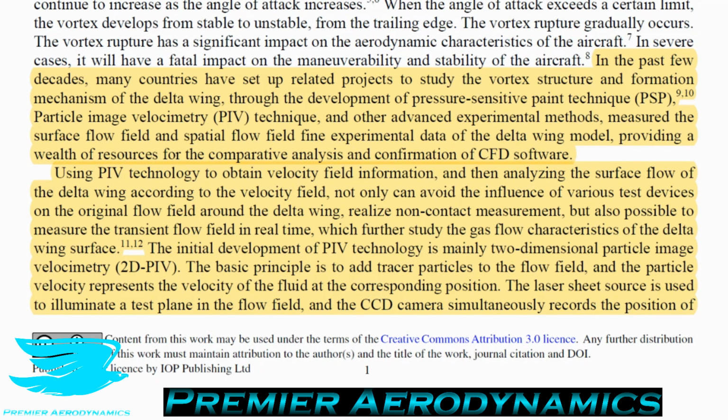PIV, if you don't, again, do it correctly, if you stick the cameras in the flow, for example, that's going to affect the flow. If you have these particles in the flow, they don't follow the flow faithfully, or they even affect the flow, then that's obviously not good either, and that's going to be, again, intrusive. But by nature, they shouldn't be intrusive, these techniques, but if you do them poorly, then they do become so. But the benefits of these are that they do have a lot of power if you do them properly. And they go on and they talk about regular PIV.